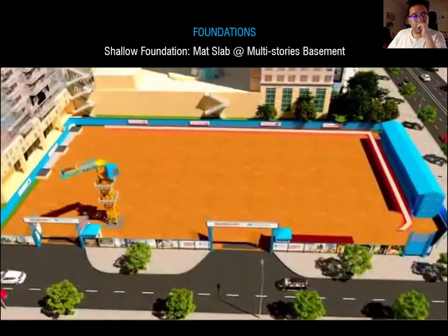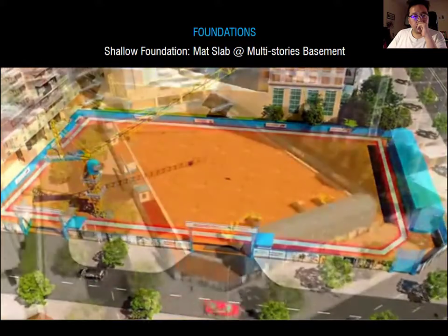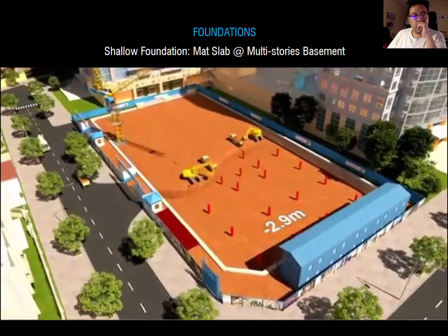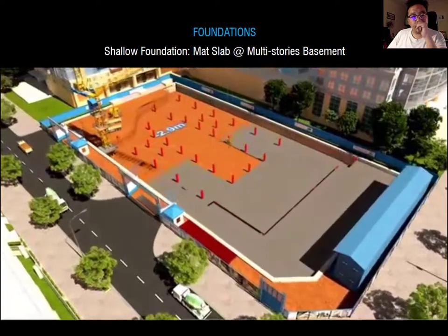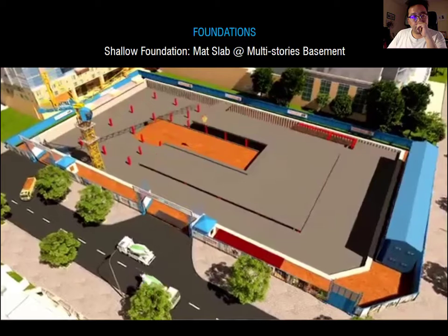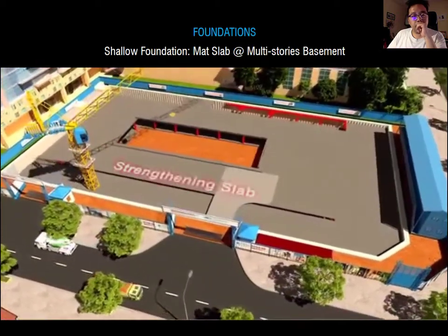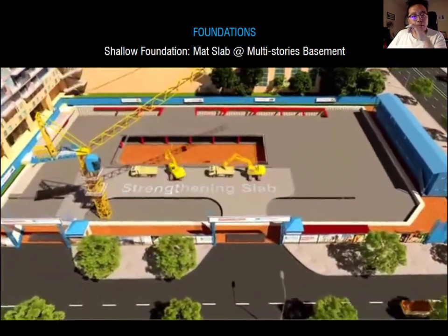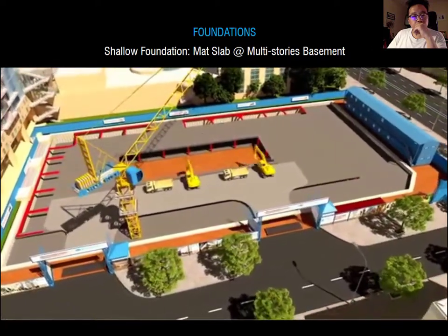The capping beam will be constructed first, while the luffing crane is being installed. Level 1. Excavation from existing GL for zones 1 and 2, followed by excavation from existing GL for zones 3 and 4. Place lean concrete work for zones 1 and 2, followed by reinforced concrete of level 1, zones 1 and 2, and lean concrete work for zones 3 and 4, followed by reinforced concrete for level 1, zones 3 and 4, and installation of struts for level 1.